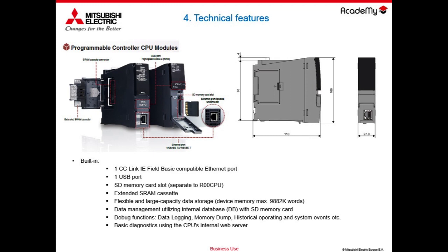So an R PLC could communicate through simple communication with an FX5. Finally, on the underlying part, which we cannot see here, there is an additional port that contains the buffer battery. Usually the battery is disconnected, so the CPU does not run and a red LED appears on the LED dedicated to the battery state.